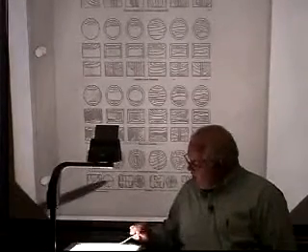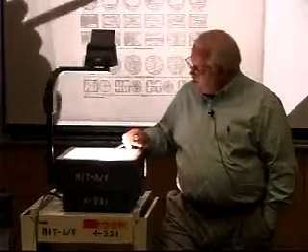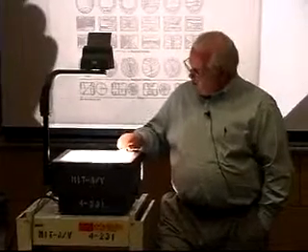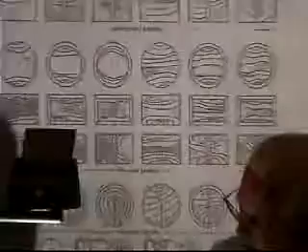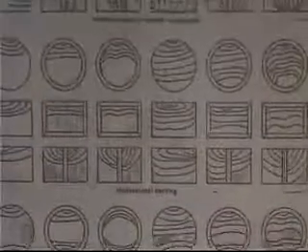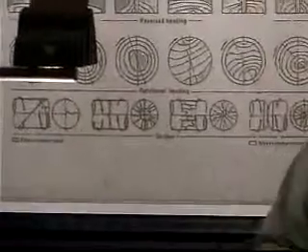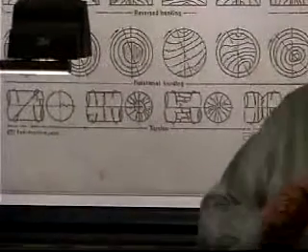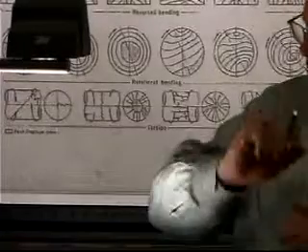If I can have different types of stresses. Here we have across here rotational bending, reverse bending, unidirectional bending, tension or tension compression, and up here, oh, actually I guess that's tension, torsion. So torsion, so it's each one above those lines. Different types of stress states. Okay, so you're either pulling on it, bending it, twisting it, bending it back and forth.